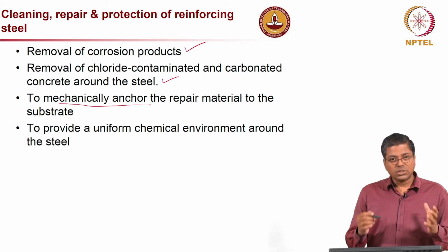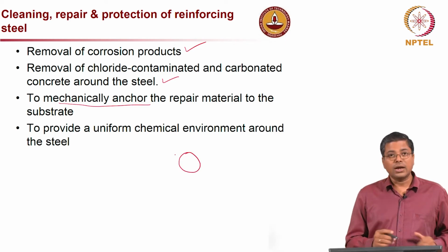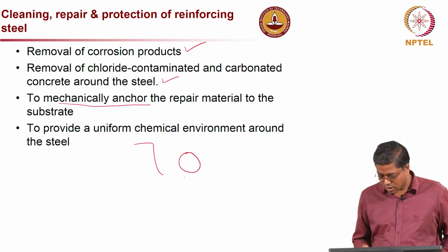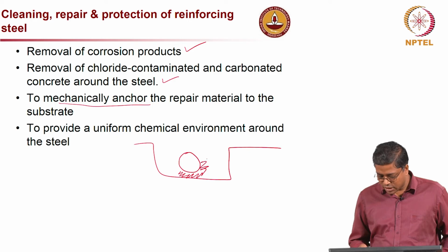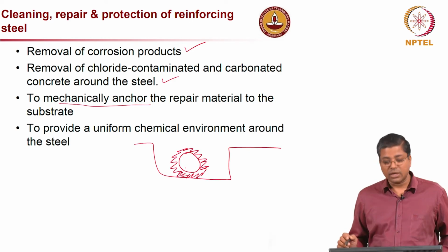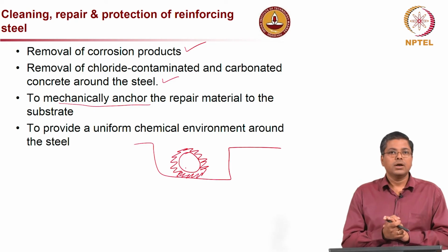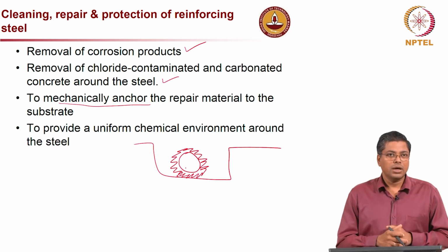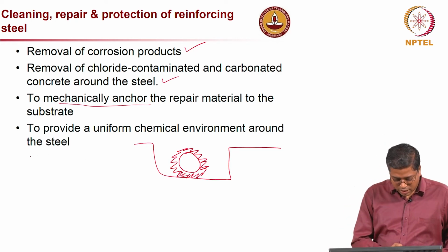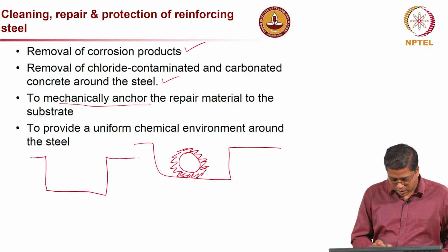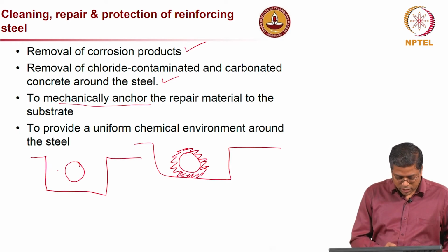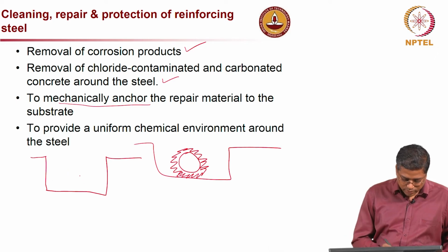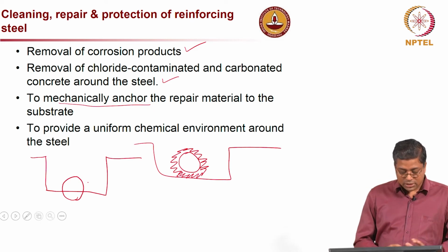And when you talk about undercutting, let us say this is how the rebar was, and when we are undercutting, that means after the repair material, the entire surface of the rebar, the full circle, even behind the bar, is exposed to the same cementitious system. If you do not do an undercut, imagine the bar is something like this, that means it is not an undercut case.